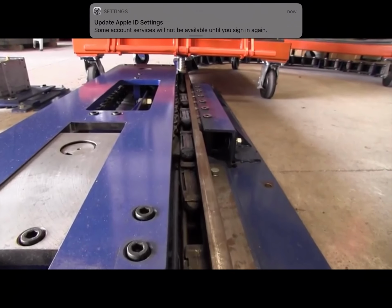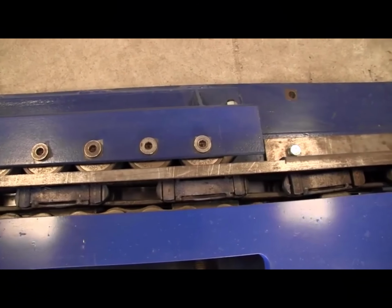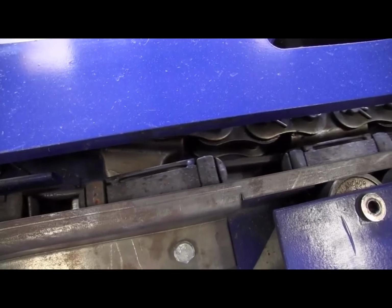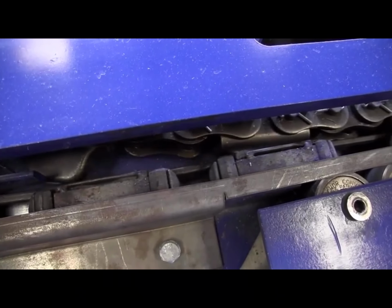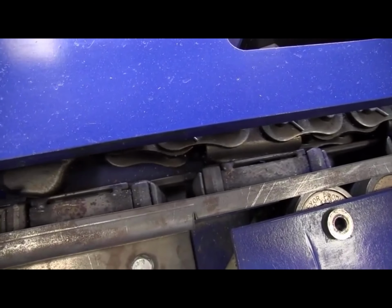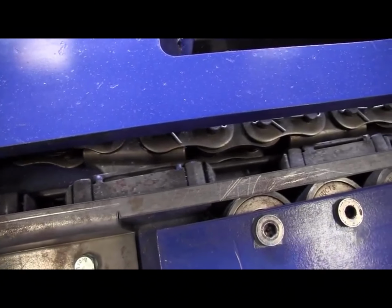Second is the unique chain system. The heavy-duty PT100 chain has the strength to move mountains. Yet it's quiet, it's smooth running, and it also has a built-in chain slack adjustment. You'll notice at the drive unit exit, the chain has a unique telescopic feature that allows the chain to retract and adjust for the chain stretch or slack. There is no need for a take-up unit with this system since the chain has its own capacity to compensate.